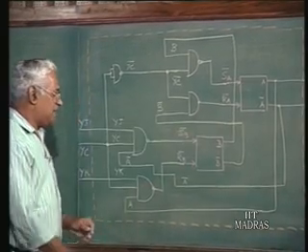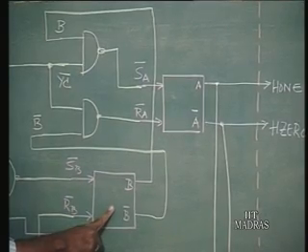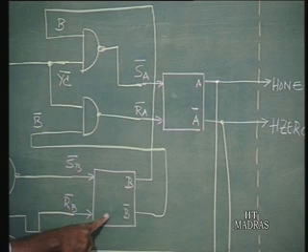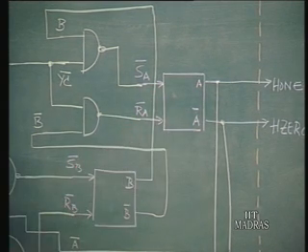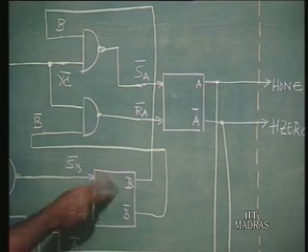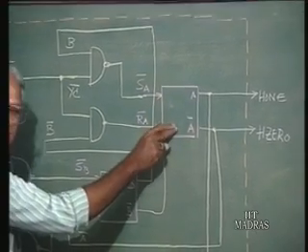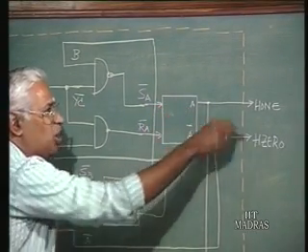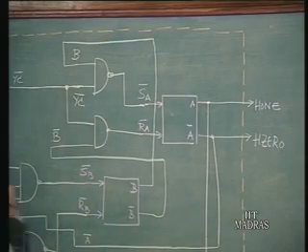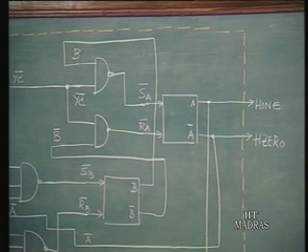You can see that this element B in fact is the master part and A just follows B, that is the slave one. B as a master follows the inputs and internally prepares the states and decides something about the state of A, and depending on the state of A the output follows immediately. So, this is the master part and that is the slave part, because the slave follows the master.